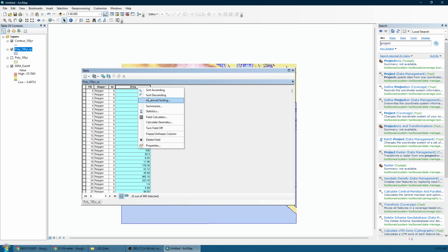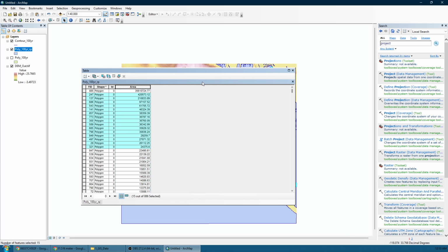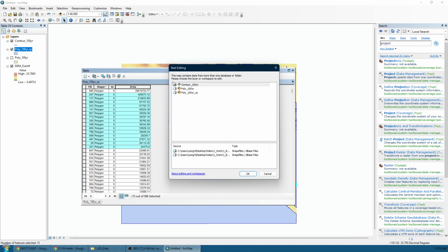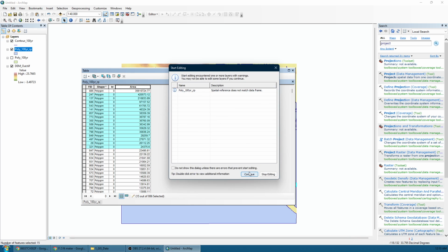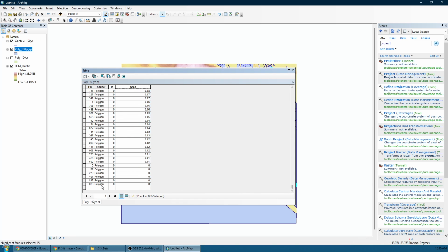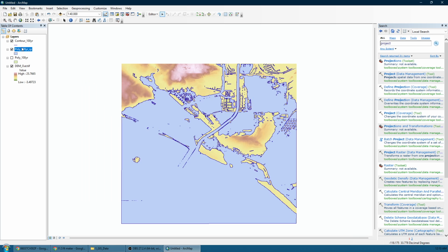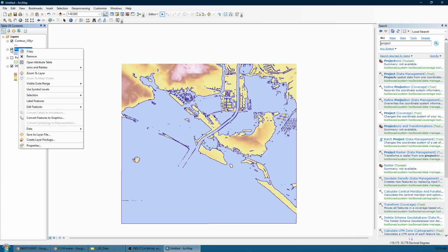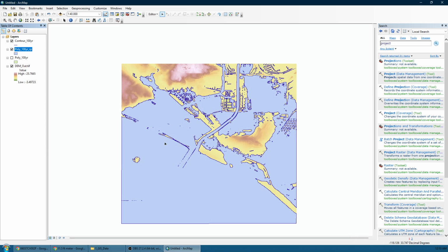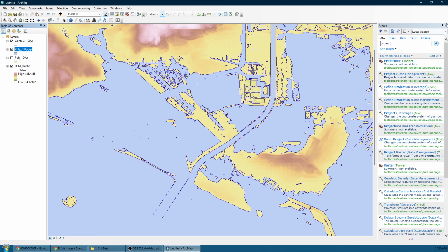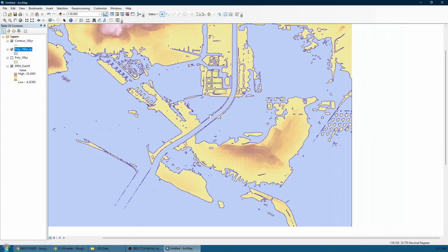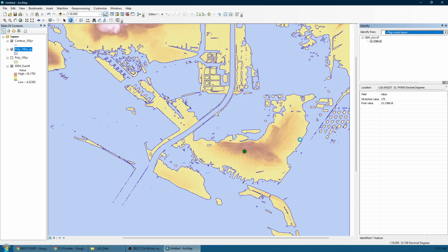The reason why you want to calculate area is you want to delete those small areas. So you want to edit the polygon, reproject, and delete selected. In this way, you have those areas deleted. Those are the areas that should not be getting deleted. For example, our target elevation is 3.5 meters, so we need to double check that this is higher than 3.5 meters.